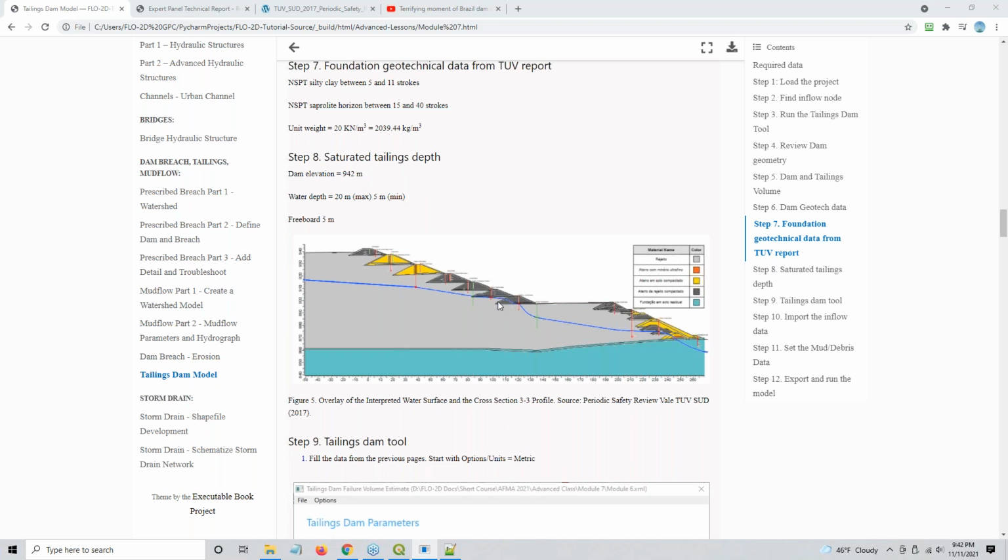And you can see we definitely have a problem with this dam, right in here. It's really not what you want to see. And then also down in here, doing the same thing. It's just getting a little bit too close to the front edge of that tailings, and we don't want to see that. So in this case, I am going to use both of these and test it with one and test it with the other and see how sensitive that parameter is, okay? Because this is all about sensitivity.